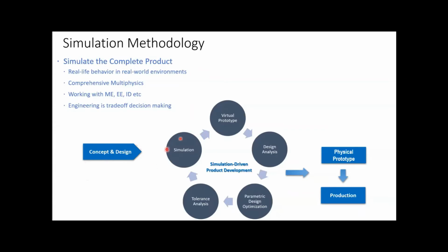So from the antenna team, we'll start simulating that, and we'll create a very detailed model of the device with the antenna in it, with the screen in it, with the batteries, with the PCB. All those details are in the model, and we'll simulate that and look at the performance. So this design analysis is looking at the performance of those antennas, be it cellular or Wi-Fi.